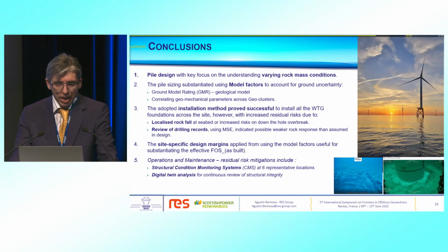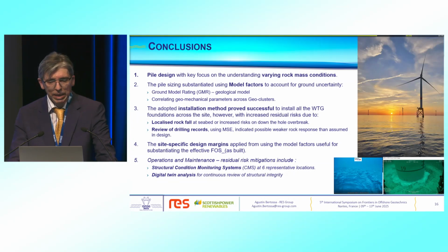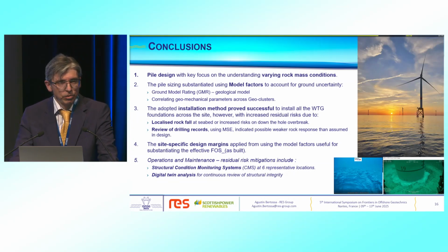So in conclusion, the pile design was dedicated to understand the varying rock mass conditions. We used the model factors to account for the ground model variability, but also to correlate the geomechanical properties across locations with similar conditions. The installation was successful. However, there were reported a few locations with localized rockfall, and the drilling records also identify some lower energy, implying likely weaker rock than expected.